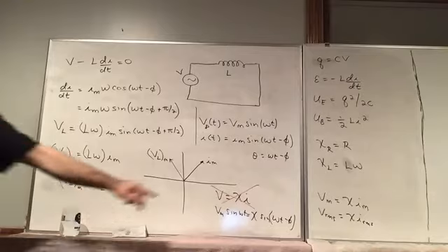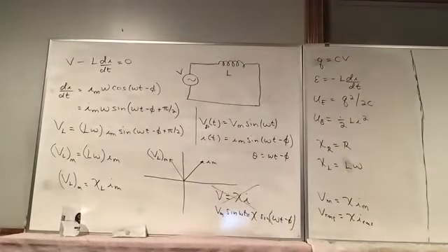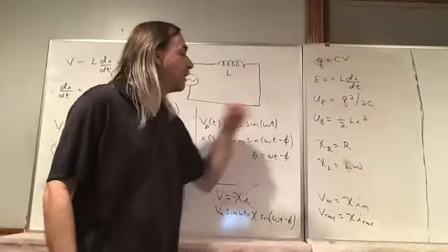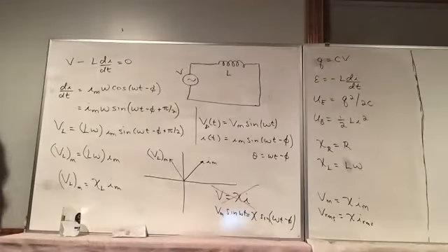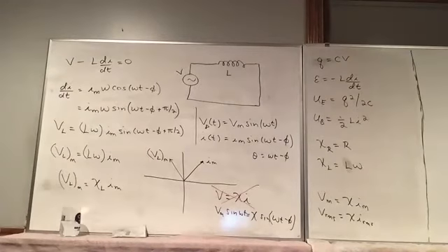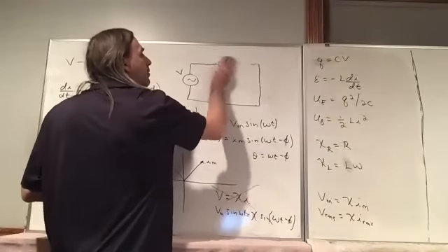So we can just have an Ohm's law for alternating currents, but it applies to either peak or RMS values. And for a resistor, it's just Ohm's law exactly. And because the current and power supply are in phase, if all we have is a resistor, then Ohm's law would apply as a function of time as well, but not for an inductor. And of course, the next step is going to be looking at a capacitor by itself.